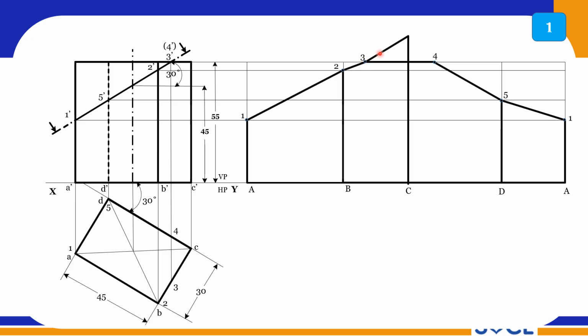From 3 you can draw a thick line straight away. So if I fold it, this point will come and sit here. So this will become my 4, right? This is my 4. So I have to take only this distance to project this 4 here.